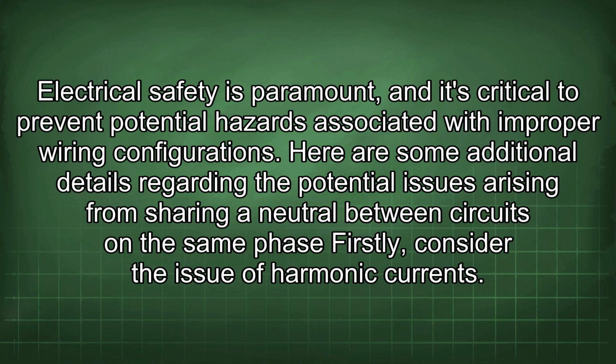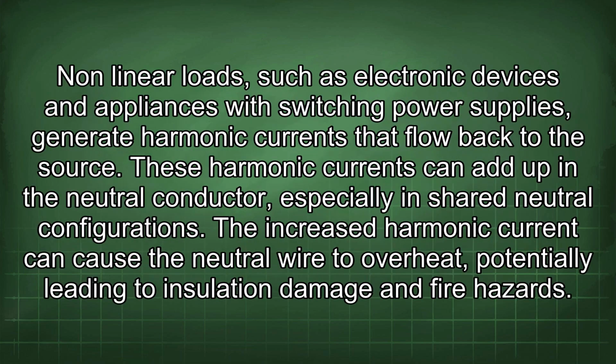Firstly, consider the issue of harmonic currents. Nonlinear loads, such as electronic devices and appliances with switching power supplies, generate harmonic currents that flow back to the source. These harmonic currents can add up in the neutral conductor, especially in shared neutral configurations. The increased harmonic current can cause the neutral wire to overheat, potentially leading to insulation damage and fire hazards.